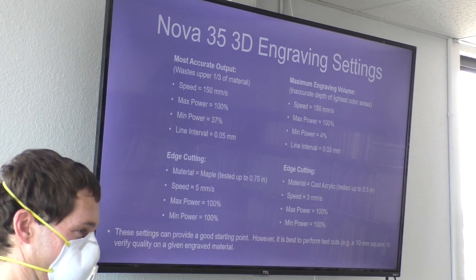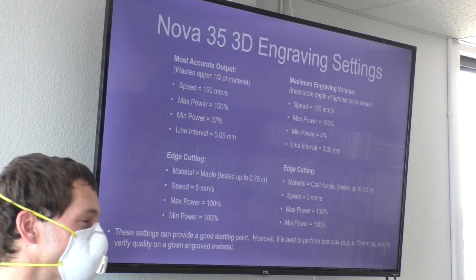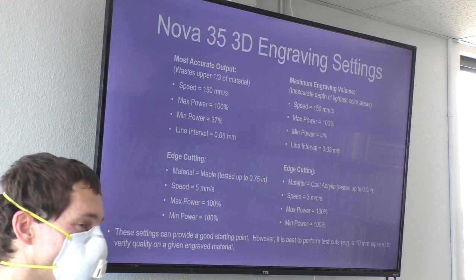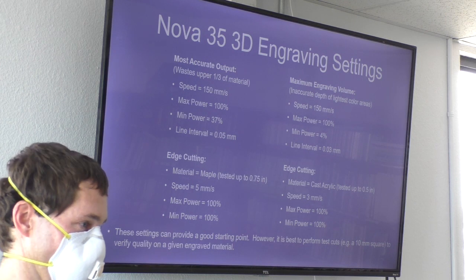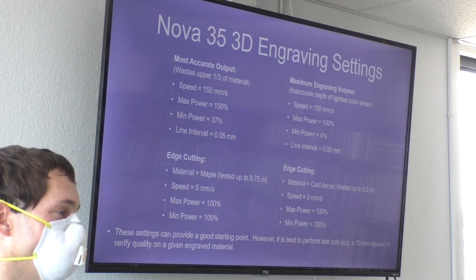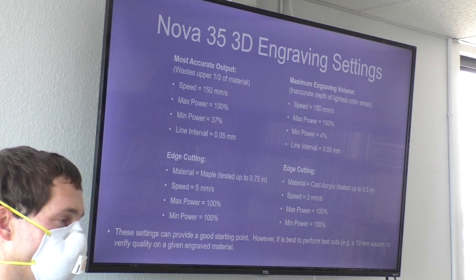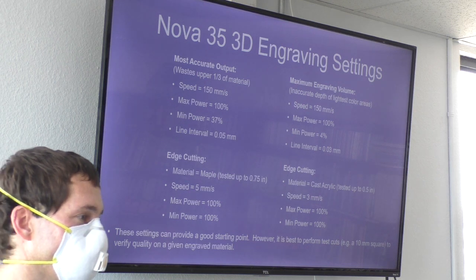I think that's one of the hardest things I've learned over the last couple of years, because I was new to woodworking. Probably a lot of these people who are seasoned woodworkers know, but especially with the laser and the CNC, even on the CNC, you want to make test cuts to see how it's going to carve.